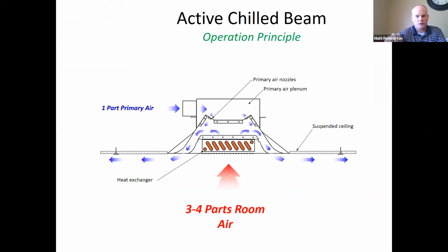And we keep those completely separate to where there wouldn't be any hot water and chilled water. And so that's how you could do cooling and heating with 4-pipe in the same 2-row coil, going with a 12-tube cooling and a 4-tube heating, or you can do 2-pipe changeover. Either way. And there are many different ways to make that work and make it economical. We've even seen 6-way valves that have been included in this in order to allow different control schemes. But it's basically, if the switch is made with the control device that you have using this, whether it's a variable valve, pretty uncommon because we'd like to just flow these full, but you can also use a solenoid valve, and that's a cheaper idea.